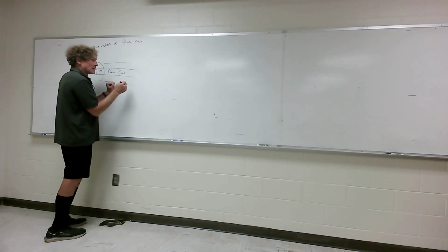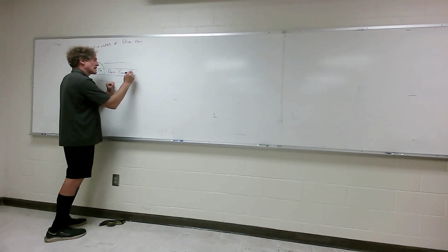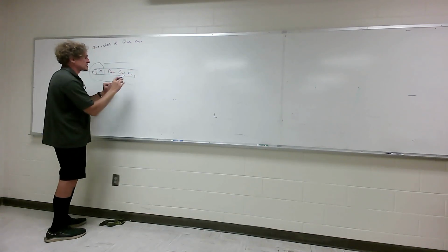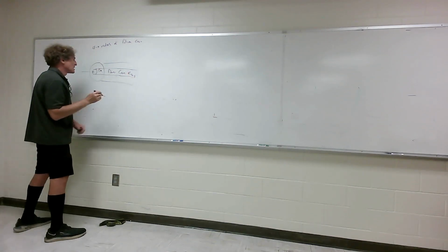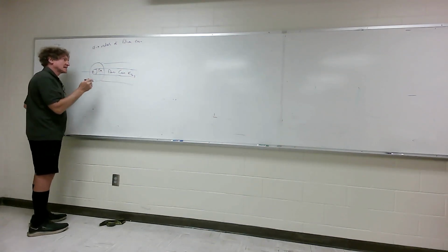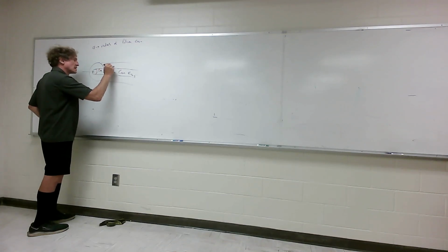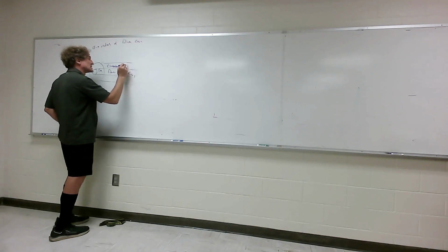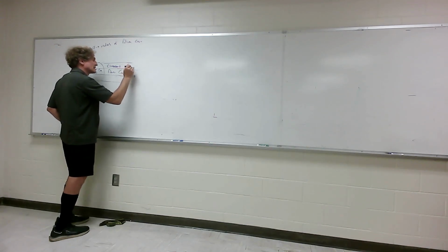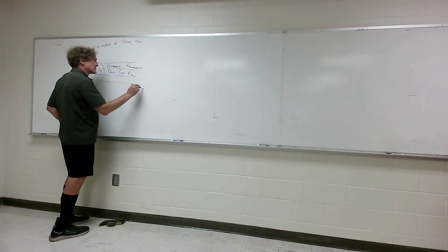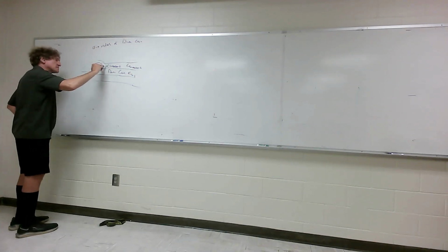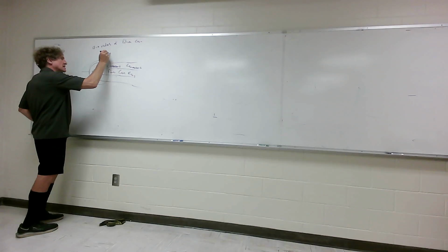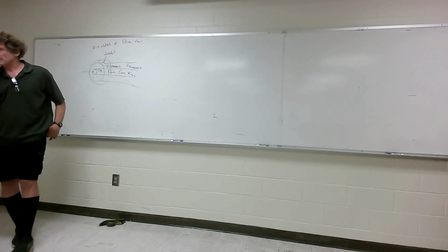I'll call it epsilon of the core, and the intrinsic impedance, I'll just call it eta of the core, or eta relative of the core. Then outside of this, you're going to have another layer, called the cladding, and that's going to have some epsilon relative of the cladding. Then around this whole thing, there's a material that's just to prevent critters from eating it. It's called a jacket. It doesn't have any bearing on the electromagnetic properties.